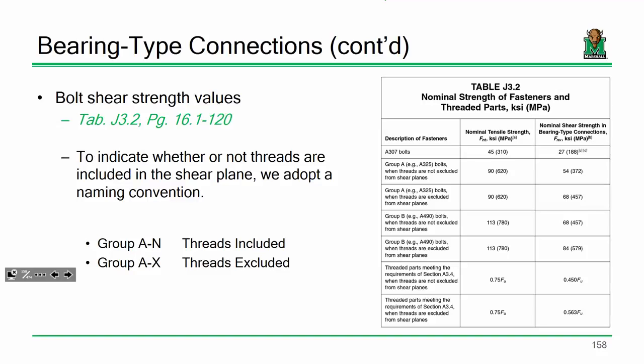Usually, would your tensile strength on your plate not govern over the bolt strength? Because an A490 bolt would obviously be a lot stronger, but you're going to design for the strength of the plate, not the bolt. Well, you're sort of, in a roundabout way, opening up a can of worms, because there are two different ways of going about this.